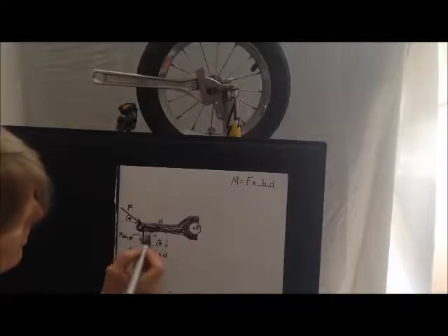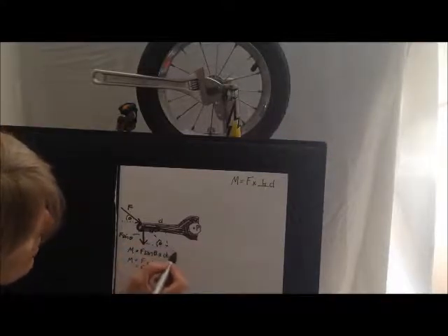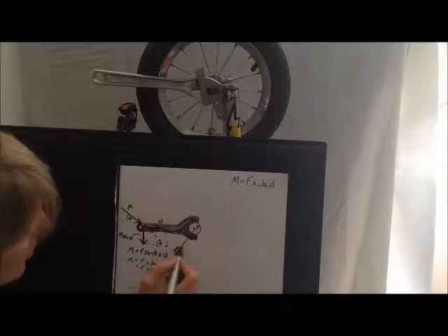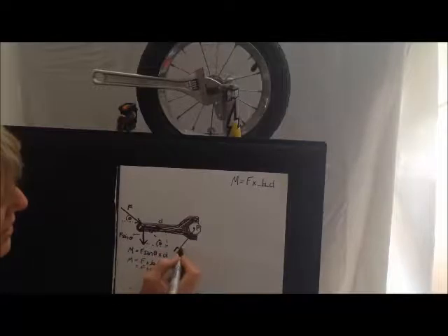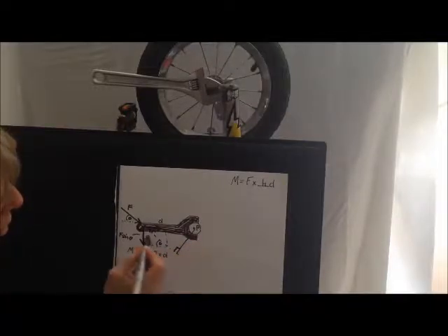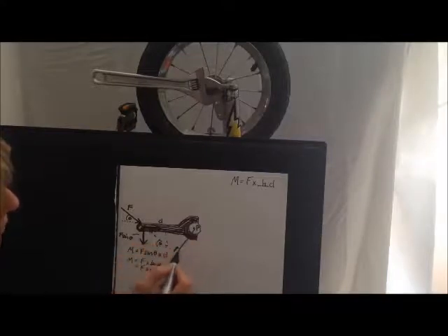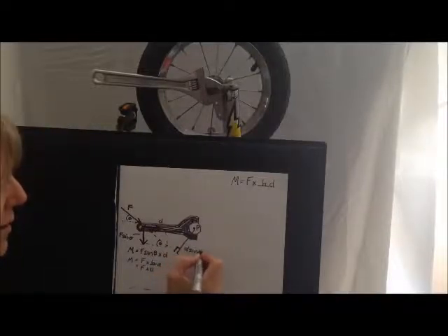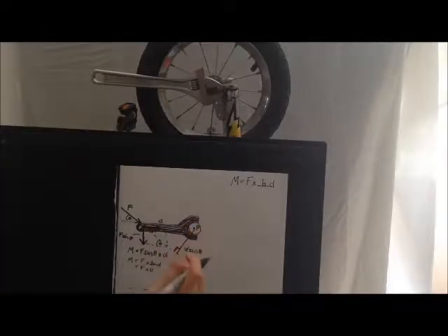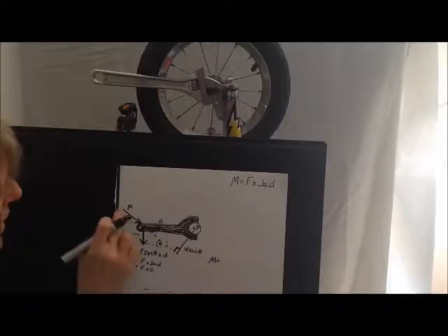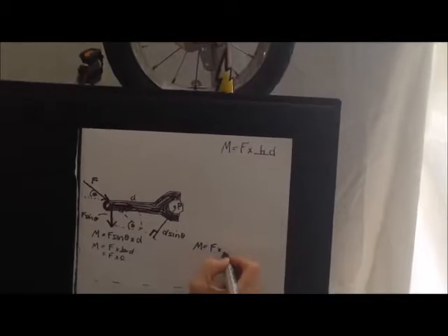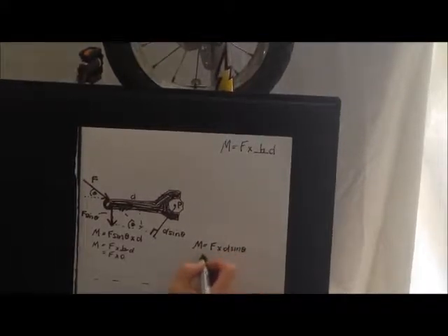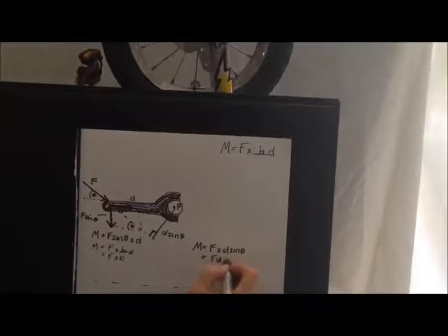Well, we can do it this way. We can take the force through its line of action all the way through to the place where it has a perpendicular moment arm. So we know the force, and this time we have to calculate this distance here. If we know that this angle here is theta, you can see we've got a right angled triangle. Once again, what we have here is d sine theta for that length. So once again, the moment is now the original force times the perpendicular distance back to the point, which is d sine theta. So the moment is F d sine theta.